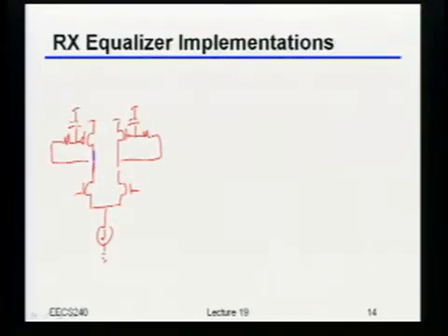Now, as we'll see, and actually maybe you've seen already, for a lot of these high-speed link kinds of things that we're talking about, they're pretty high-speed circuits. And if you think about it, the reason we generally don't like PMOSs in high-speed circuits is because their FT is lower. In other words, they're going to introduce more capacitive loading than we would have introduced if we could have, for example, used an NMOS transistor. Okay? Well, it turns out you can actually build an active inductor using an NMOS transistor also, and still without burning extra bias current.